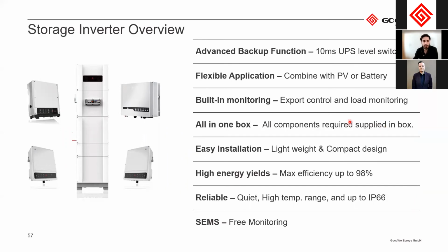And some overview here of our inverters. They all have this advanced backup function that can switch in less than 10 milliseconds. So this is UPS level switching. You can combine it in many different ways, either with PV, PV plus battery, battery only, and so on. And they all come with a built-in monitoring device.